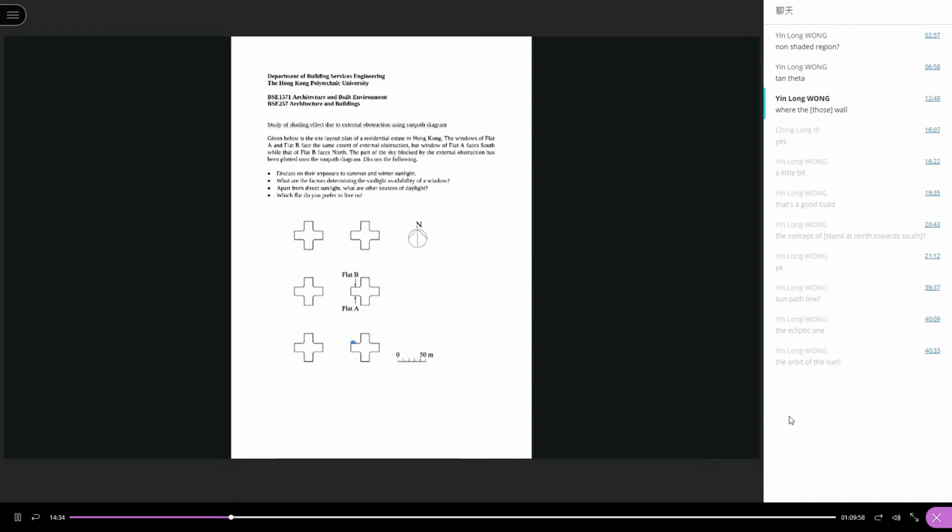And then I may cut another section, and once again calculate the theta angle. I need to cut another section because this D will be different, right? For these lines, I have different D. Although these 6 buildings have the same height, so the H will be the same, but D will be different. So the theta angle will also be different, right?